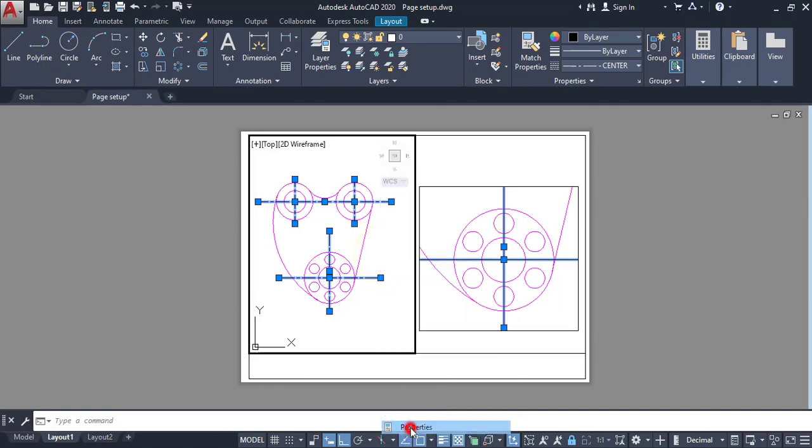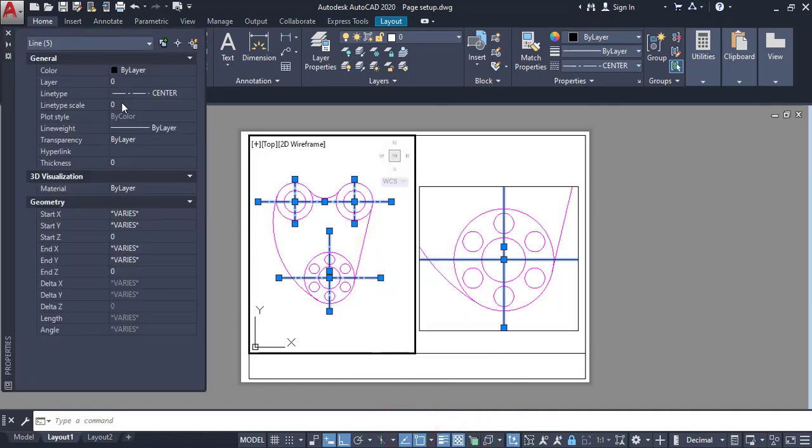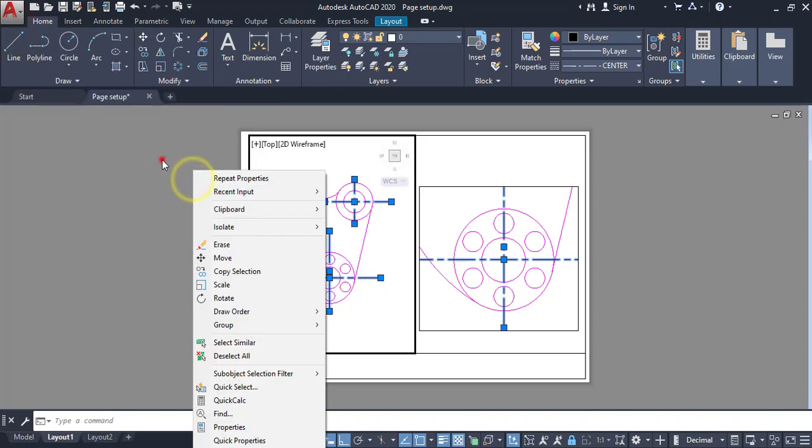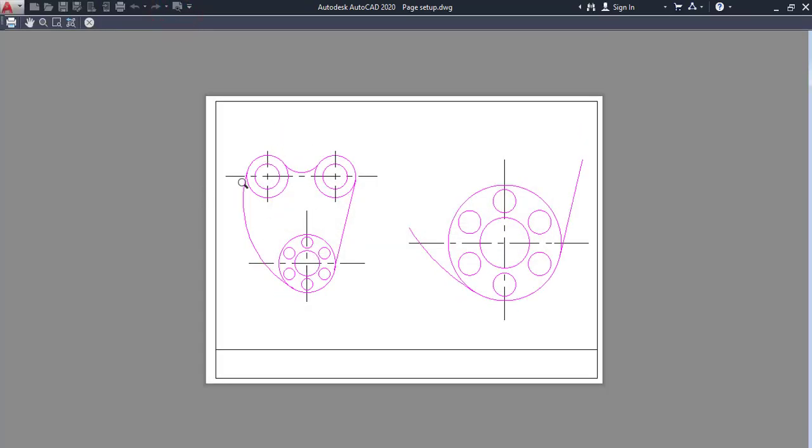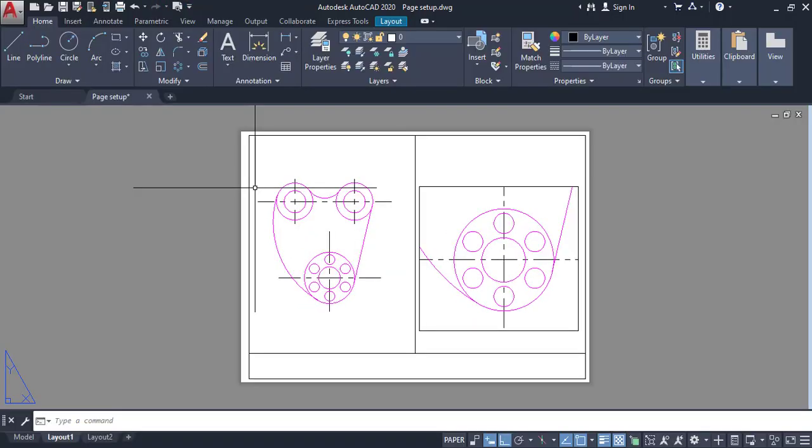And right click properties. Here line type scale is 1. Then enter. Close. Double click it here. See the print preview. Here it's actually placed very well. Now page setup is complete. Page setup, viewport placing and object zooming and scaling, those works are completed.